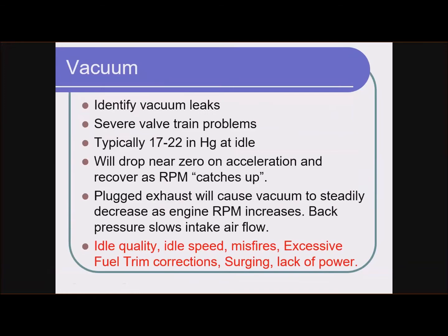If you look at that second line, severe valve train problems. If you have a stuck valve, let's just think about this, an intake valve that doesn't close, right? Then every time that piston comes up, it's going to push air back out into the intake manifold. What are you going to see on the gauge? You're going to see a needle that bounces severely. I'm not talking just a tiny little bounce, right? But every time that piston comes up, it's going to shove pressure back into the intake manifold. So you'll see a bouncing needle. That can identify valve train problems.